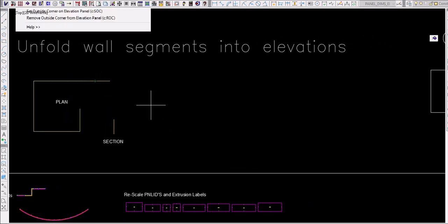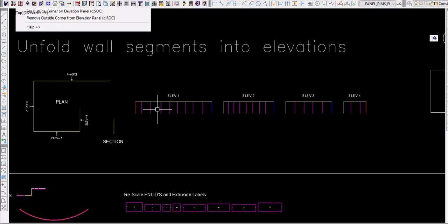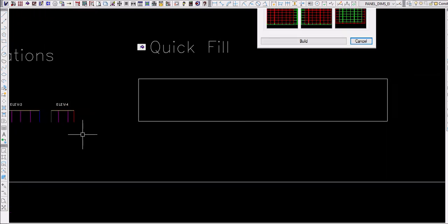Click, and then say put it right here, and there's the elevations for different elevations, and we can then decide what the section looks like. Is it a 3, 4, 5 rows of panels, because each one may be different. Then we could just use our old tool panel grid utility and project that and have all the panel shapes made. That was easy.